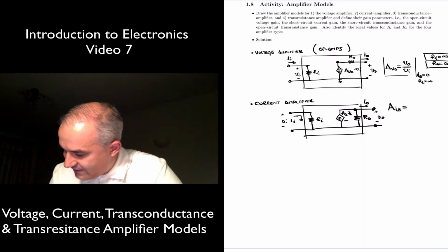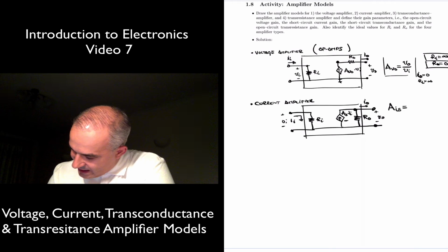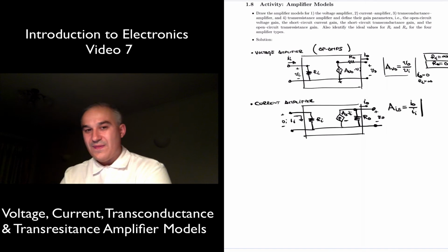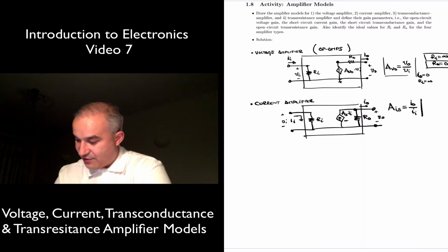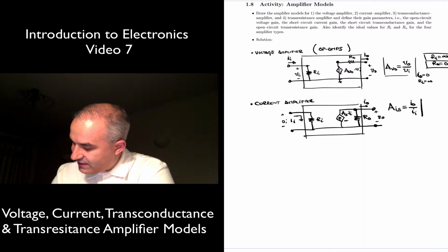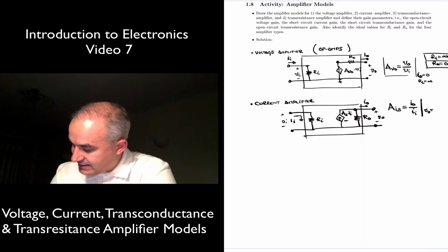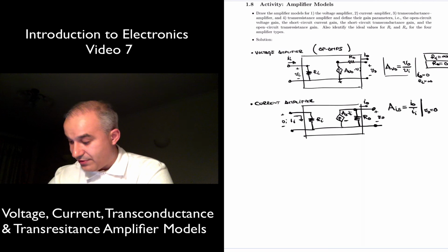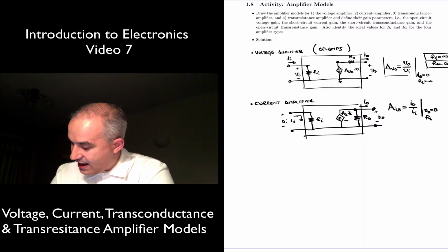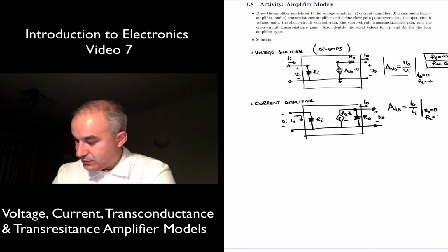So this is defined as the output current over the input current when the output is shorted, or the short circuit current gain, right? How do we define that? Well, we could say that the voltage output is 0. That's the same as putting a wire between those terminals, or equivalently that the RL, if we connect a load there, is equivalent to 0.